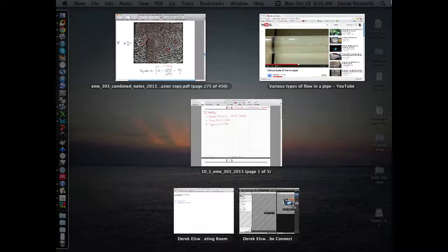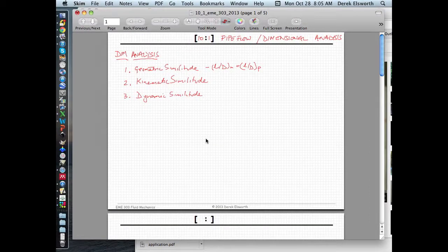And so we look for the fact that we have kinematic similitude, which is typically the Reynolds number of the model is equal to the Reynolds number of the prototype. And finally, if we satisfied both of these, then the big ask is that we want then for some other condition to be similar. And so that's our calculation. So if we know what the Reynolds numbers are, or we can have a diagram for the Reynolds numbers, then